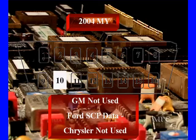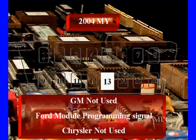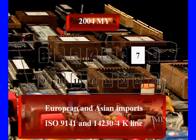Then we go to pin 10. GM doesn't use it. Chrysler uses it at times. At times it doesn't use it. It's usually used for flash programming or communicating with some extra modules if it is used. But Ford uses it for their SCP, the other half of the data signal. Pin 7. GM doesn't use it, but Ford uses it for the ISO bus. And fortunately, you're going to find that other people use it for the ISO bus. Pin 13. GM doesn't use it, but Ford uses this for their module programming signal. And in Chrysler, it's either not used or has some unlimited special usage.